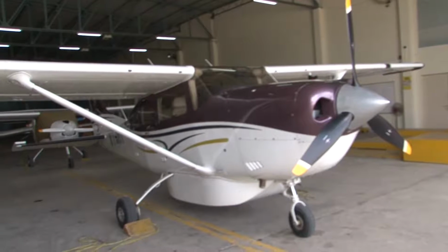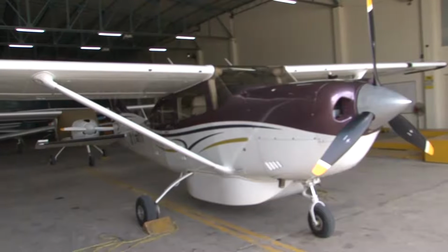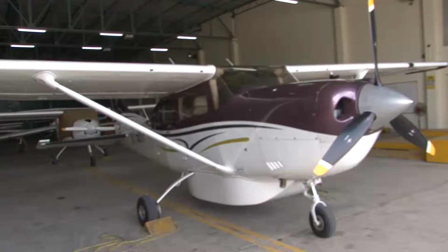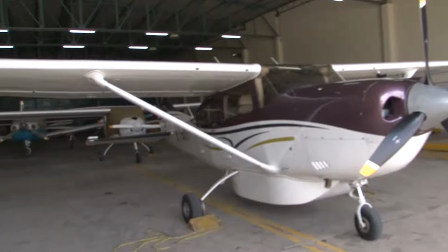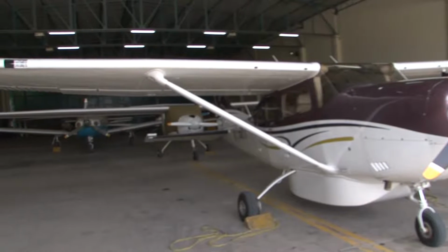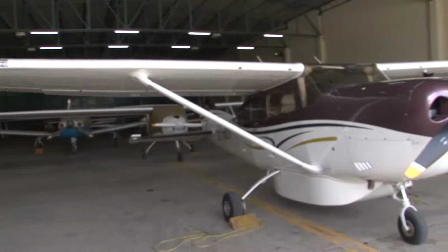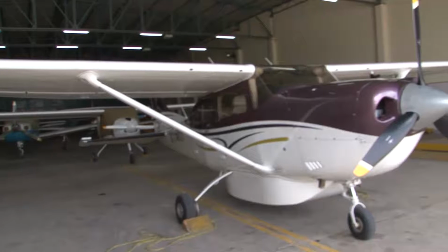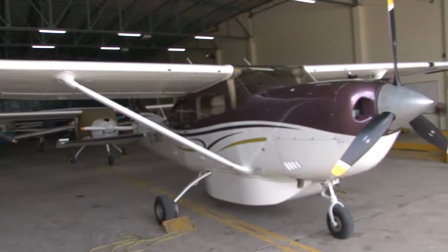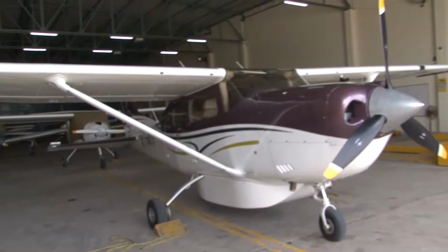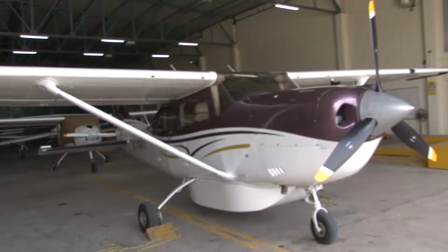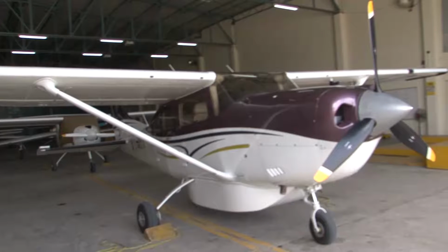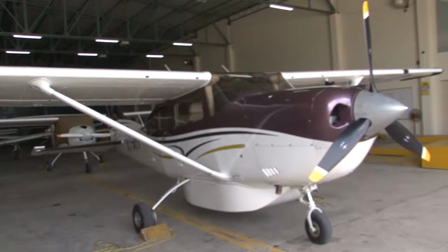But my next question would be, if this is the span, what is the area of this wing? Because we have been talking about wing loading. So I need to know the wing loading of this aircraft, because we have been talking about that for the last few lectures. Once I know the span, I look for the area, and for this airplane, the area is around 174 square feet, which is equivalent to around 16 square meters.